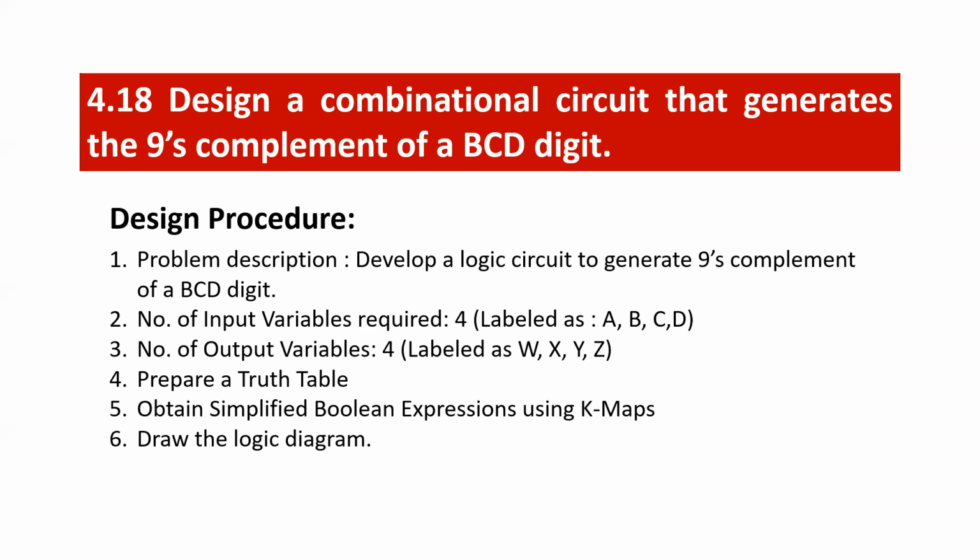The design procedure has many steps. The first one is the problem description, which describes the given problem as: develop a logic circuit to generate a 9's complement of a BCD digit. Next is the number of input variables required. Based on the given problem description, we should identify the number of input variables required. Here, the input is BCD, so the number of input variables required is 4.